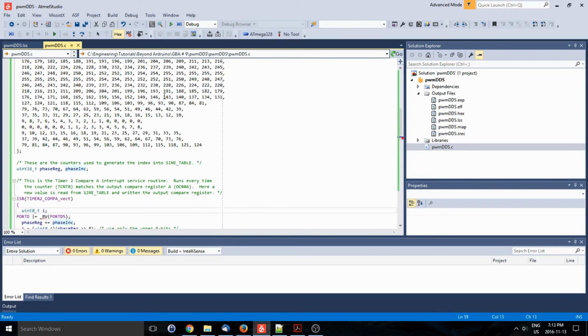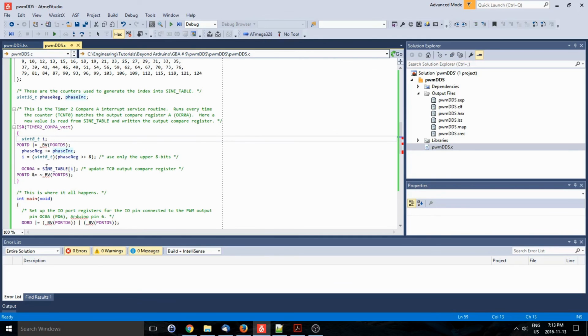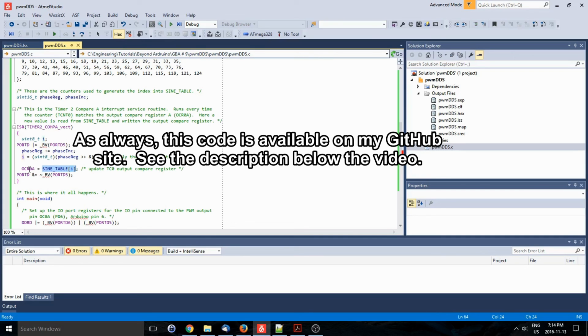And we don't have to use the PWM to generate analog outputs. We can also use one of the I/O ports and what they call an R2R resistor ladder, which is another type of digital to analog converter, which I might show how to use. It's pretty simple. The code would be pretty much the same, just where this phase, the sine table output right here, goes to, instead of an output compare register, it'll go to one of the I/O ports to send a value out to the pins of the I/O ports, and then the R2R resistor ladder will convert it into an analog signal.